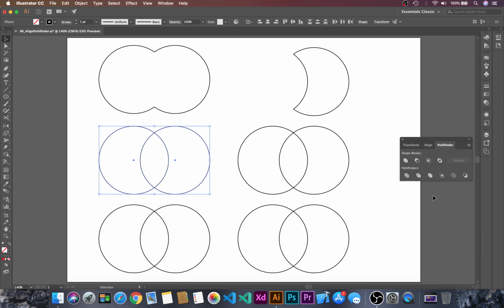Let's select this and then go over here, and then it will only have the shape that has intersected, or the common shape. We can see only the intersected shape is available. Now select another one. What it will do is delete the intersected shape and then divide the other shapes.